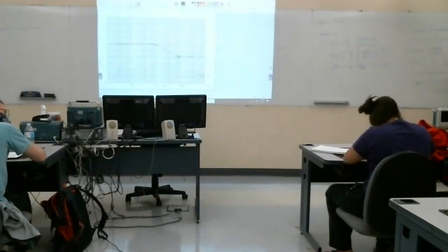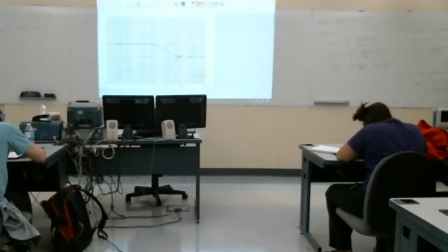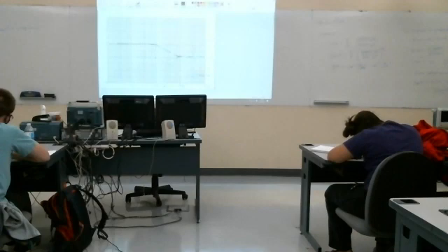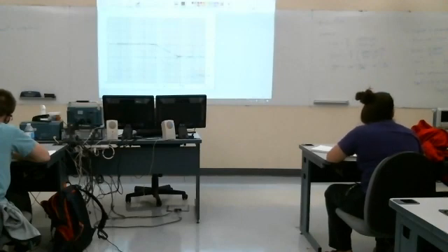So if we come over here, certainly at low frequencies, H of 0 in dB is 20 log of 10, right? With omega equal to 0, that's 20 dB. H of infinity in dB is 20 log of, if I let omega become infinitely large, ignore the one terms, I'll have omega over 8,000 divided by omega over 1,000.